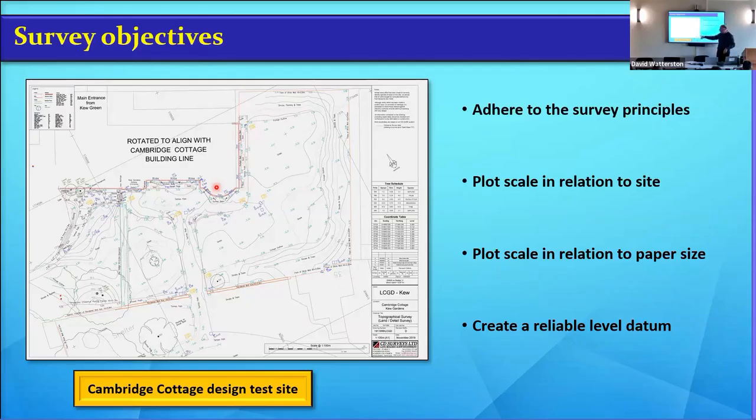But again, if 1:100 gives you a survey, a tiny wee survey in the middle of an A1 size sheet, you could reduce that down to A4, A2 or A3. But if you wanted clarity, you would say, all right, I'll have it at 1:50, please, on an A1, so I can see what's going on. You could still pay for the 1:100 accuracy, but have it displayed at 1:200. They should put a disclaimer on it that this is commensurate to the plotting scale that was requested, 1:100, whatever. So a friendly survey company should do whatever you want.